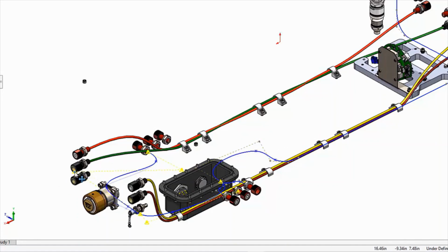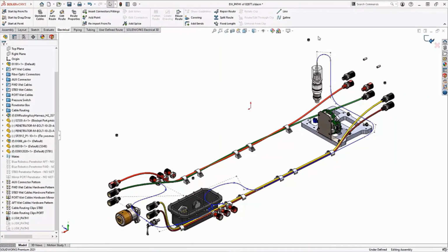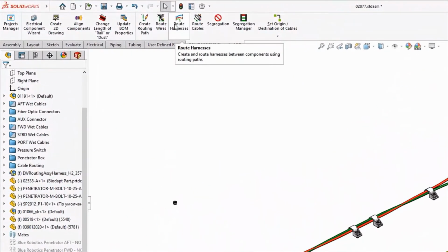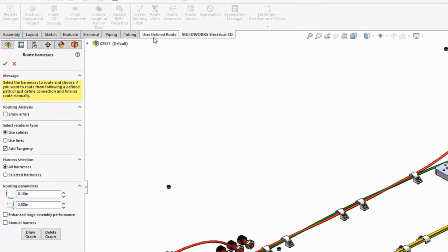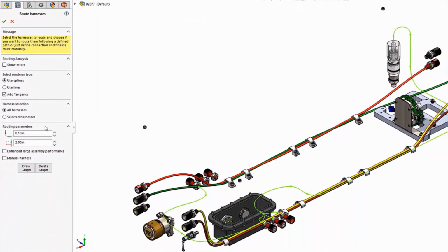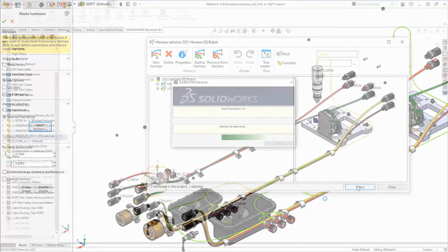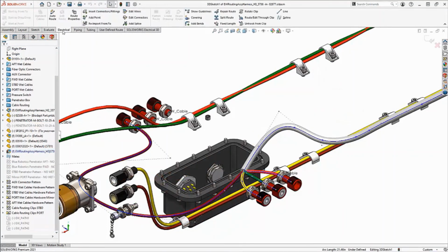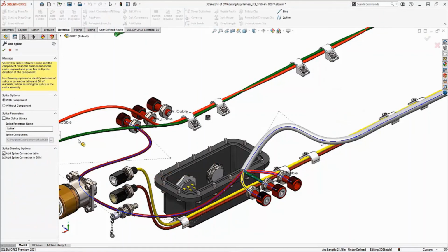To finish up this harness and reduce waste of material from cutting 3 conductors shorter than the longest wire, we will add the splice to the wire so all conductors in the harness are cut to equal length. Supporting splines along with lines and arcs in creating a routing path for electrical harnesses greatly improves the versatility of routing electrical harnesses in geometrically complex products.